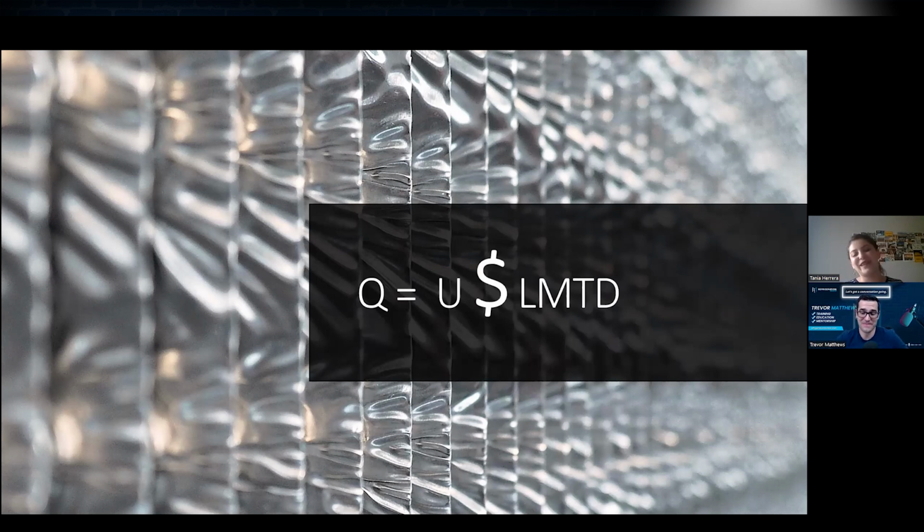Exactly. But there are also limits, because if we're talking about evaporators, we cannot have many fins. We call it fins per inch, because with more fins there is more likely to be ice formation, and we don't want our evaporator to be blocked with ice. So we have some considerations when we have a freezer. We cannot go above, for instance, 3.2 fins per inch. But if we have a cooler, then we can increase it.